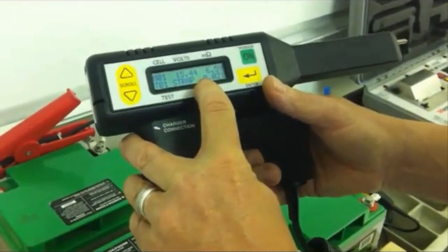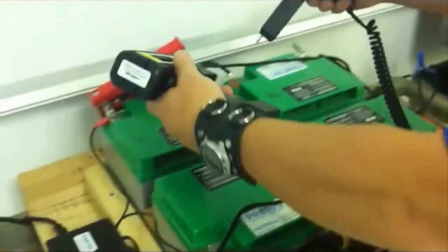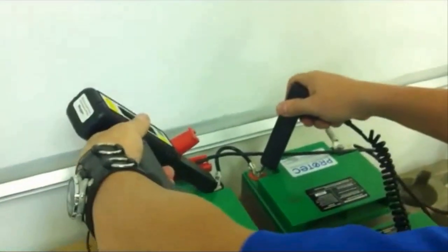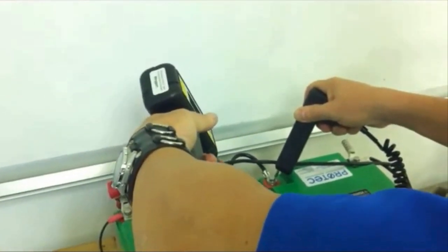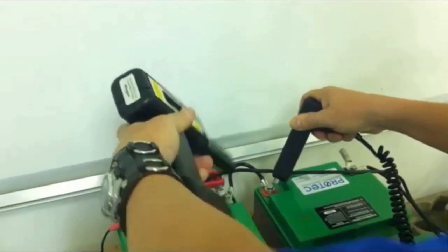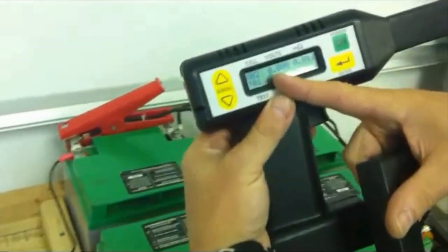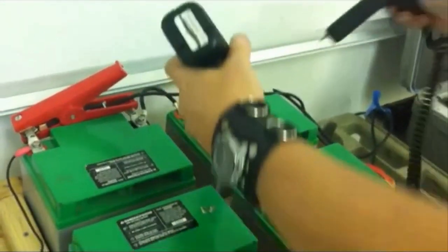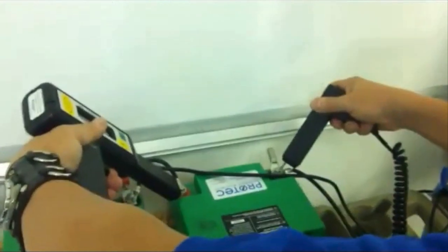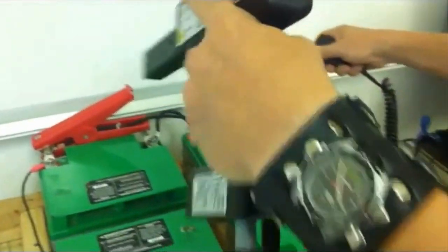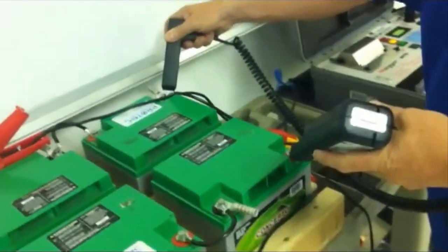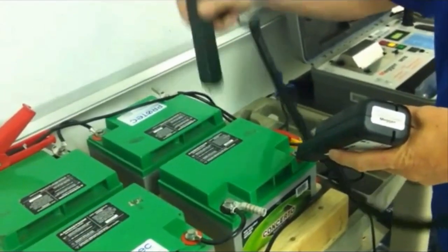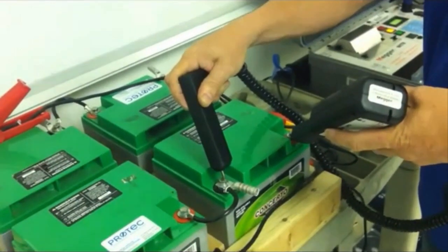It is now asking me to take the strap measurement. So I will now go across the interconnecting strap going from jar 1 to jar 2. I'll capture that value. And now it prompts me to move on to jar number 2. And I will continue through the test in this manner, capturing the DC voltage, internal cell impedance, followed by interconnecting strap resistance. As you can see, the test moves rather quickly.